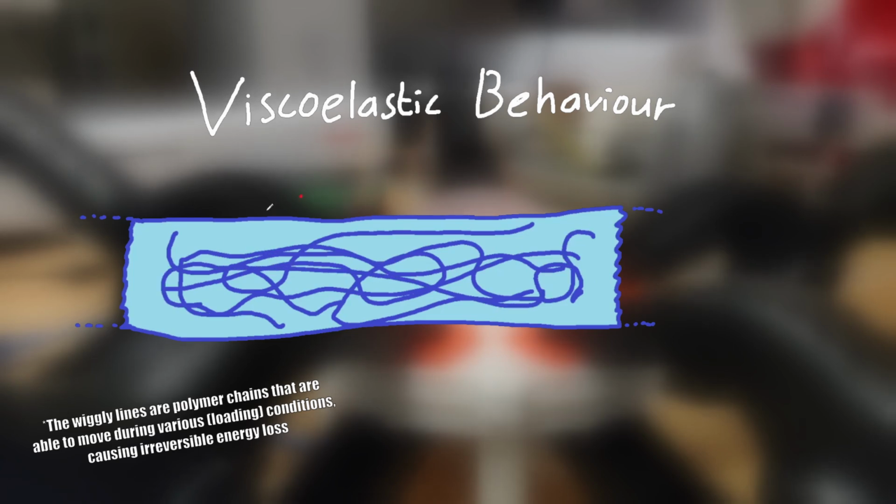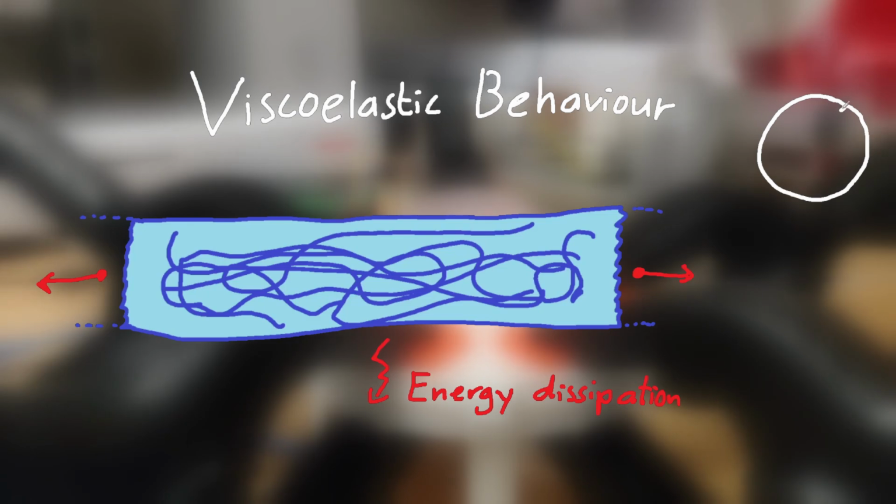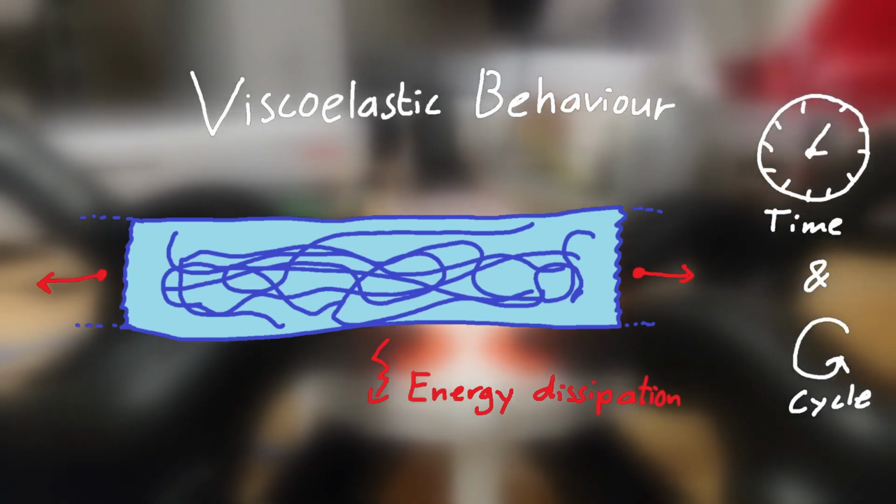Elastomers typically exhibit hyperelastic behavior, meaning that it's capable of making large deformations while returning back to its original configuration once unloaded again, ideally being completely reversible. However, most elastomers also exhibit some form of viscoelastic behavior, where energy is partially dissipated within the material's internal movements, making it irreversible. These effects are time or cycle dependent, making the predictability of such materials only more complex.